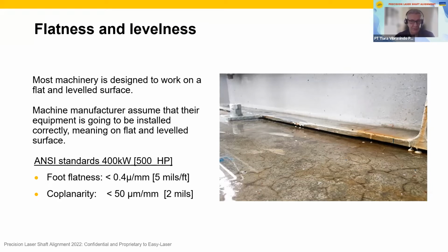If you have splash lubrication in your machine, and if you have an unleveled installation, you will move the oil away from its oil slinger. That will be the end of the story. So think about what really causes all of those problems that we know related to bearings. Very often it is actually the installation of the machine, its base, lubrication, or the handling of the bearing and machineries.